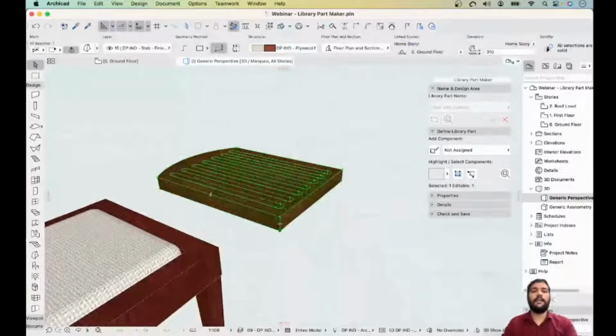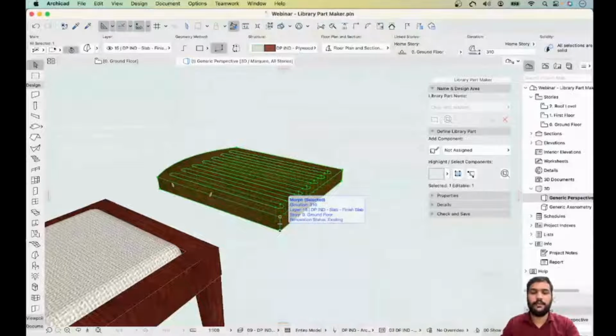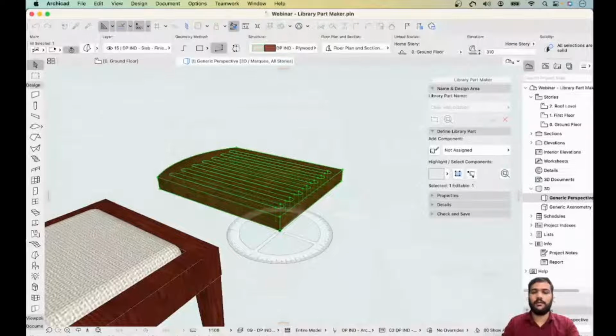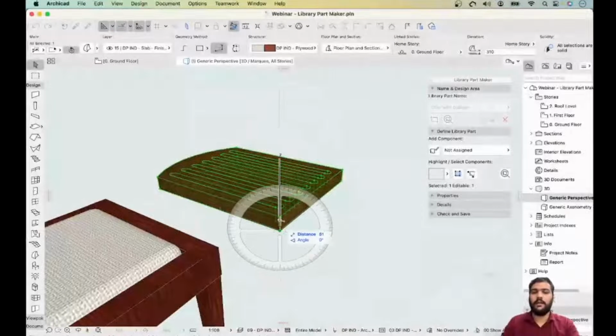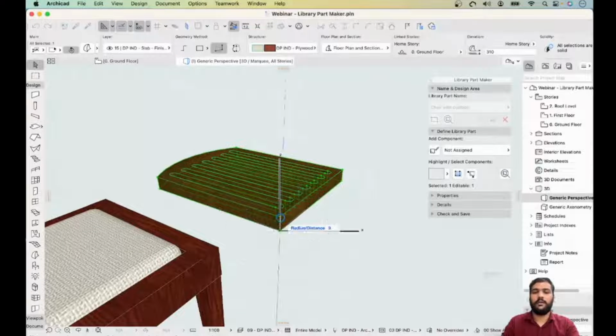And so for rotating in 3D, there is one trick. You select the object, Control E, and just click one end, and without leaving the mouse button, you click up over here. I will just show it again.